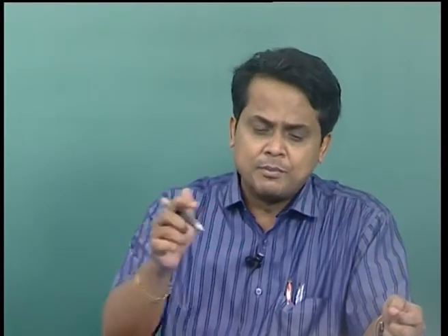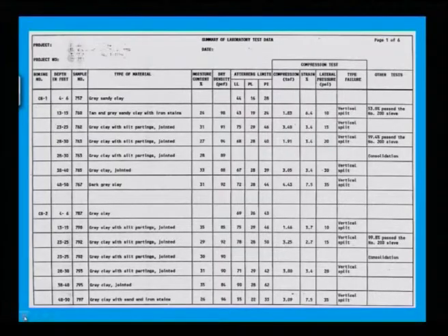It means you have done this classification based on your laboratory test, remember. That means you have to provide all the laboratory tests in the report also, because the design engineer can also cross check whatever calculation you have done, whether it is correct or not. So, to supplement this, once you say that it is silty sand, you have to provide this data, the complete summary of laboratory test data, that has to also be attached in the soil exploration report.